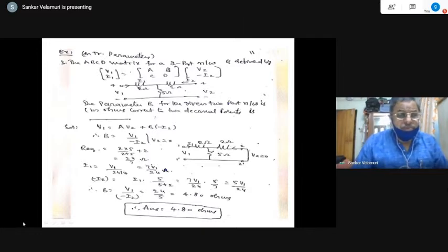Have you got the idea? So it is 4.8 ohms without doing this particular exercise. How? Convert this star into delta, and the impedance connected between the common points. That means you convert this T into pi, say. That is the equivalent of T network and pi network of the transmission network. So that is 2 plus 2 plus 2 into 2 by 5. That is converting star into delta: Z1 plus Z2 plus Z1 Z2 by Z3. So 2 plus 2 plus 2 into 2 by 5, where 2 into 2 by 5 is 0.8. So 4.8, that is the answer. Is it right or not?